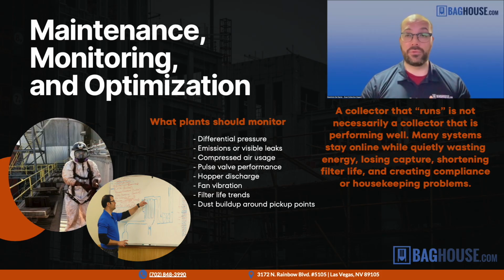Other things you can monitor if you really want to try to optimize, especially on your larger, maybe your key systems: how much compressed air you're using, the pulse valve performance. You might also want to have something that's monitoring that dust is being discharged through the airlock on the bottom, things like fan vibration, RPMs. You can also monitor emissions coming up to track the life of the filter bags. All of these things can be done on any unit, but we recommend them particularly on your most important units, your crushers, your dryers, anything that's permitted, because that's where you're really going to see the most benefit from it.